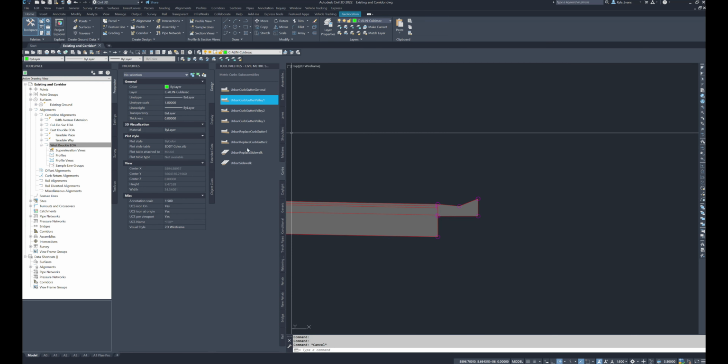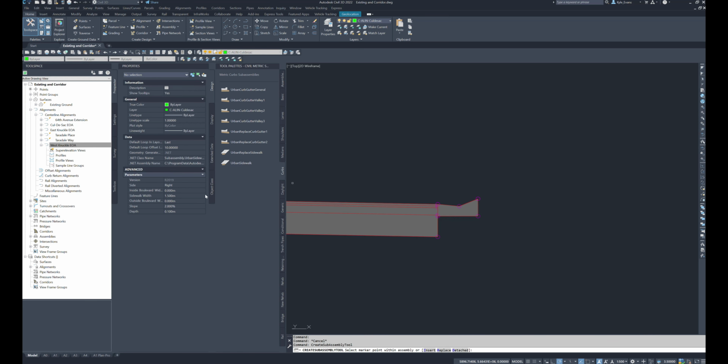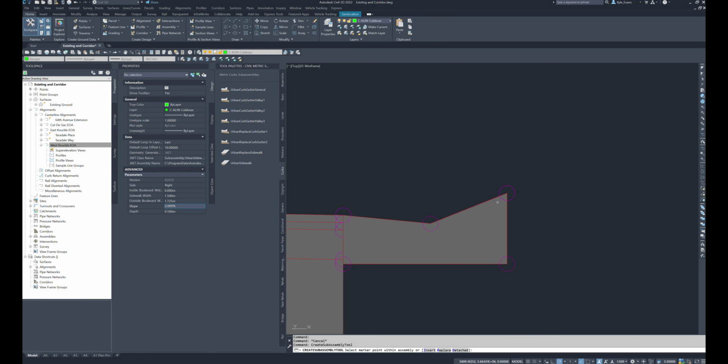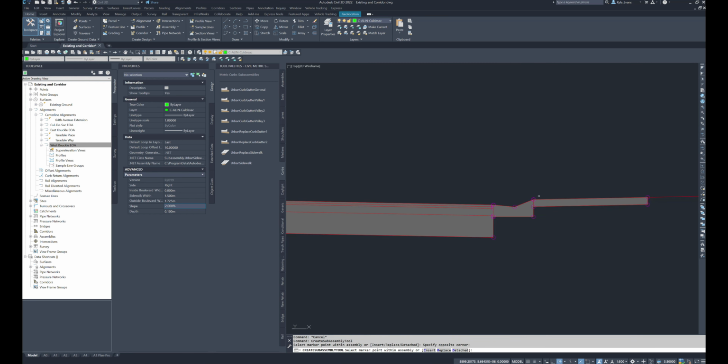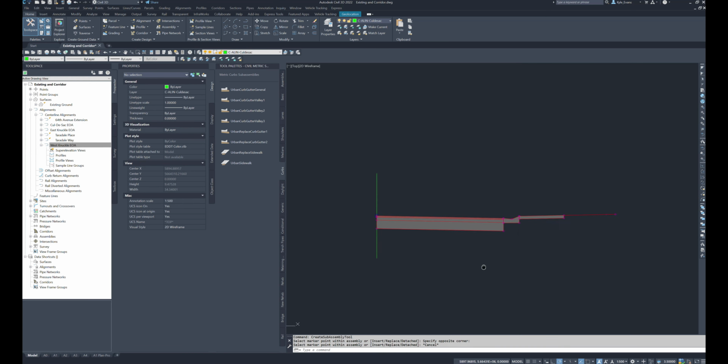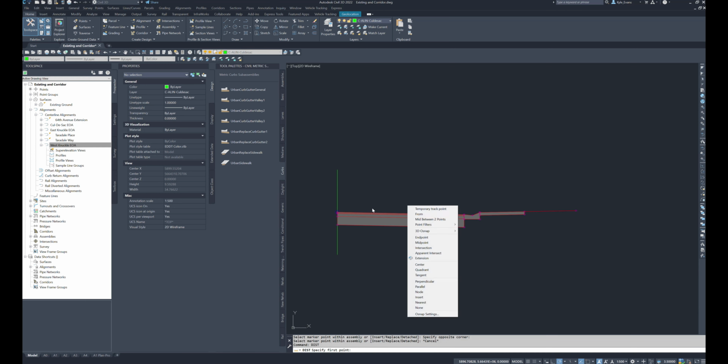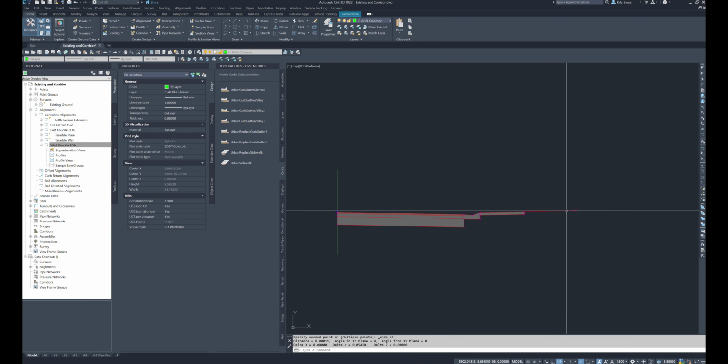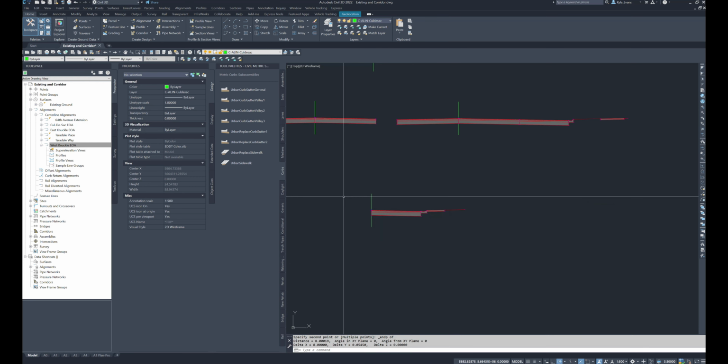Next, taking a look at the sidewalk. So again, I'm going to be using urban sidewalk. My inside boulevard width is 0. My sidewalk width is 1.5. The outside boulevard width is 1.725. 2% slope with a depth of 0.1. And I'll click and place that in. So this, if I measure it, and I've done everything correctly, should be 8 meters wide. So our distance in the X is 8 meters wide.